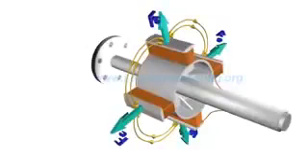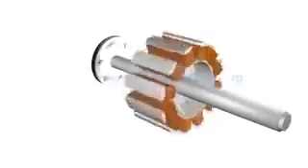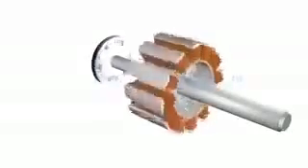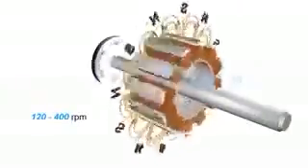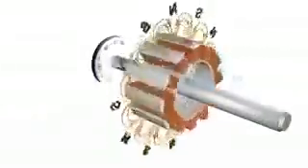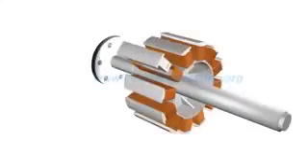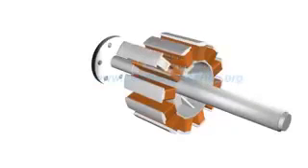So salient pole rotors generally have 10 to 20 poles, which demands lower RPM. Or rather, salient pole rotors are used when the prime mover rotates at relatively lower RPM. The pole core is used to effectively transfer magnetic flux, and it is made with fairly thick steel lamina. Such insulated lamina reduces energy loss due to eddy current formation.